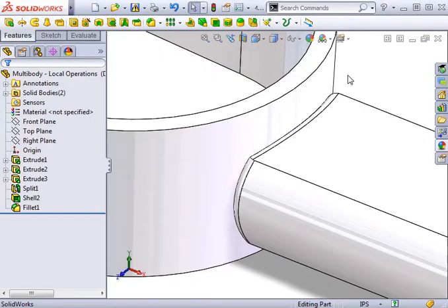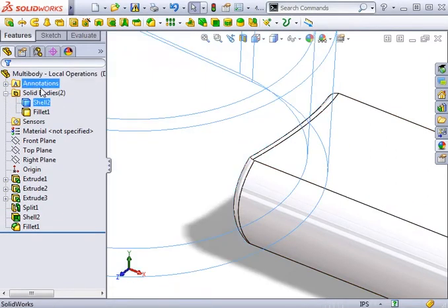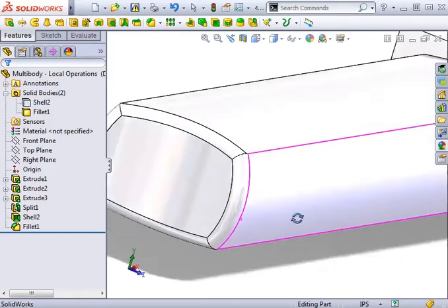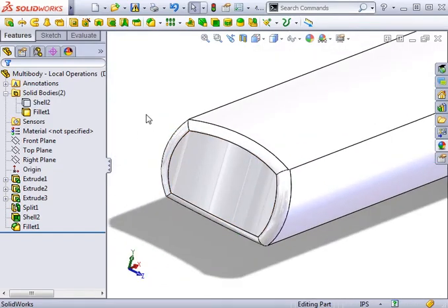In the previous lesson, we saw how adding this final fillet feature to the edges where the head meets the handle led to strange results. The results are easier to see if the solid body making up the head is hidden. Now you can see what's happened. Since this model is made up of two solid bodies, the edges I selected when I created this fillet are not edges where the two bodies merge. Rather, they're edges that belong only to the handle portion. When I added the fillets, it's as if the head didn't exist.